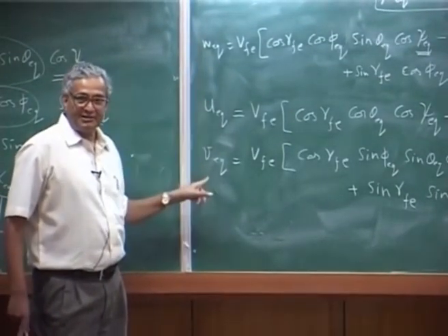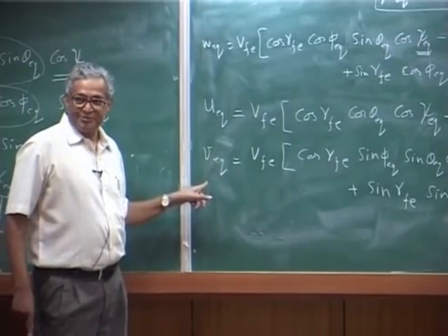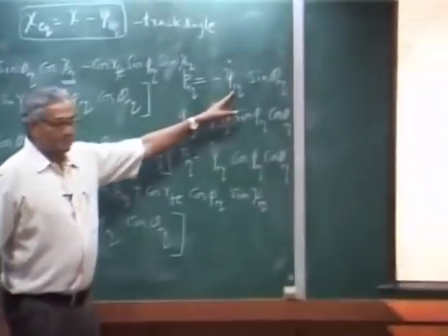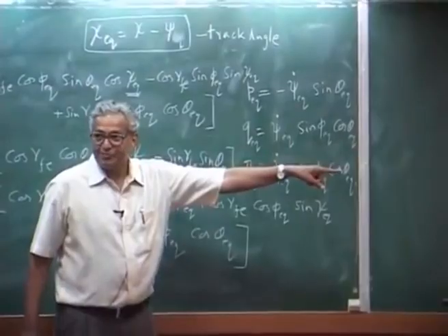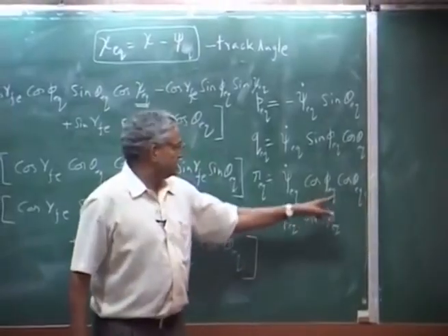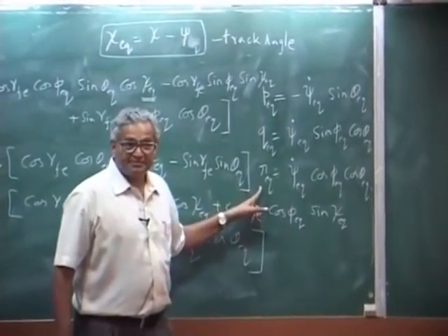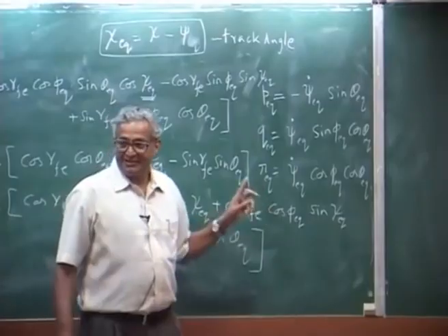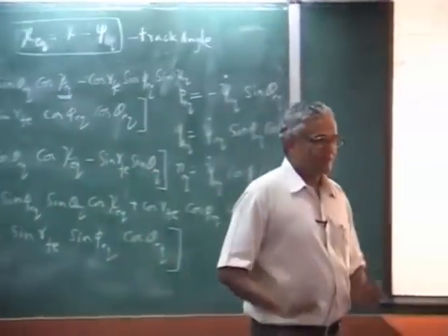That means, you have all the 3 quantities, okay, and given psi dot, that is the input equilibrium turn rate. You have already assumed theta EQ, phi EQ. That means, I know PE, QE, RE. Okay. You go back to the 6 equations and then solve. I will just briefly mention, because this procedure is quite complicated, that is where the convergence comes in. See, here I briefly describe the procedure that is done. Trim procedure, I just put it complex.